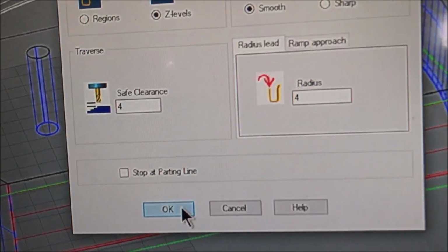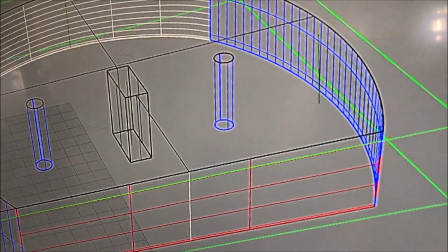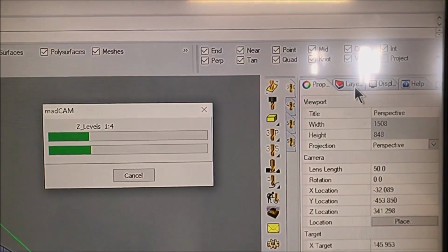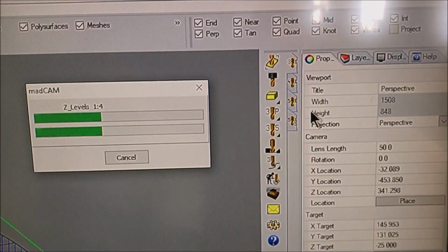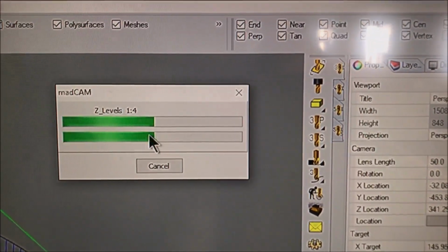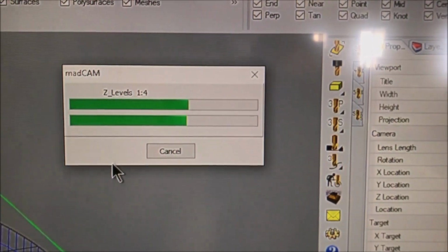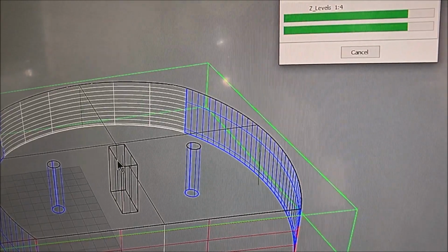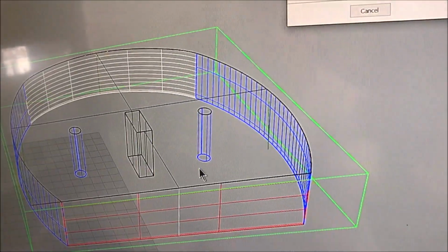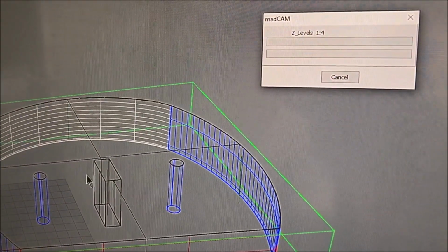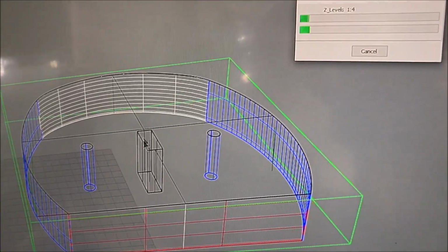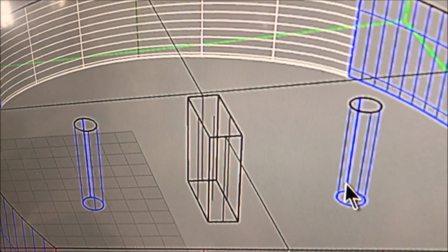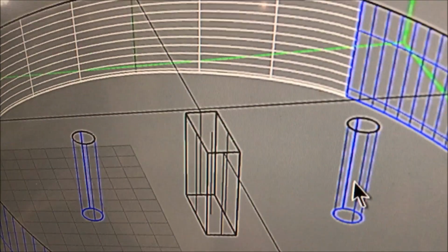Click that, and it creates a toolpath. And it creates a toolpath in Rhino as a new layer, which it's doing now. We don't have to cut the top of the foam. It's a 50mm bit of foam, so we don't have to worry about the depth. All it's doing is cutting the sides and the holes in the middle. So we've got the hole for the RHS, and we've got 2 dowel holes just to keep the thing all lined up and neat and square.